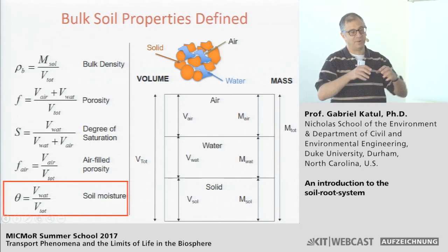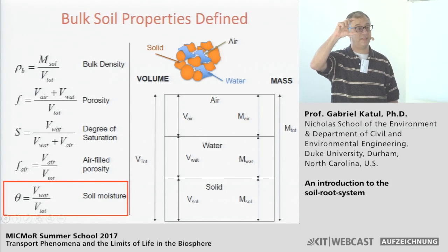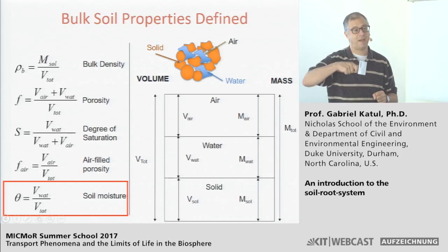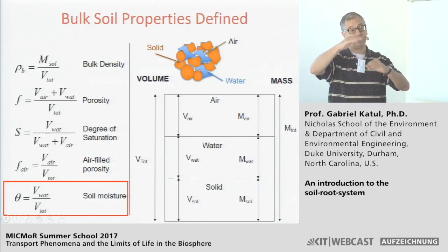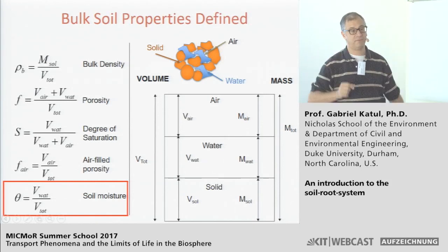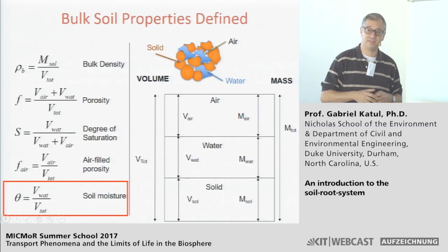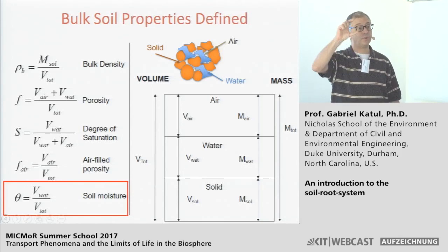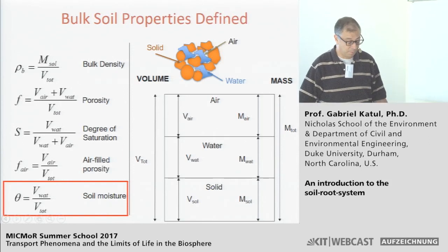You dig a small hole, you take your sampler, and typically the sampler will have a fixed volume associated with it. You dig the sampler into the soil by hammering, pounding a little bit, and then you extract a volume of soil. There are usually putty knives that you stick on the sampler, so you could then subsample the volume you have taken to avoid boundary conditions, because you probably jump on the sampler and disturb the soil. Then you take a fixed volume of soil. So the total volume of soil is easy to measure, and often with these samplers, it's about 60 centimeters cubed.